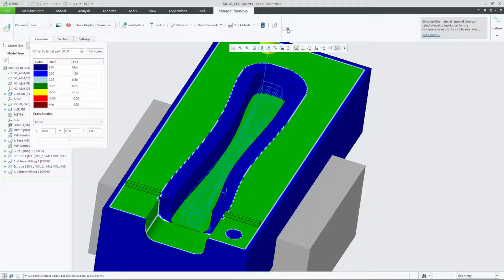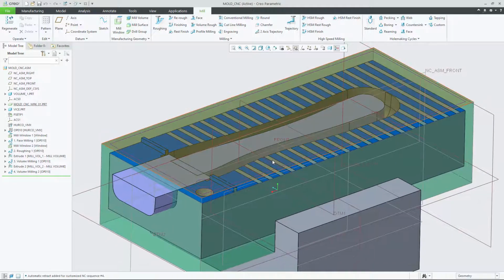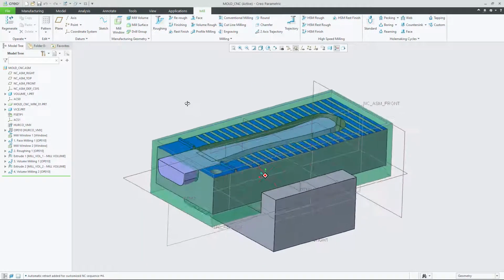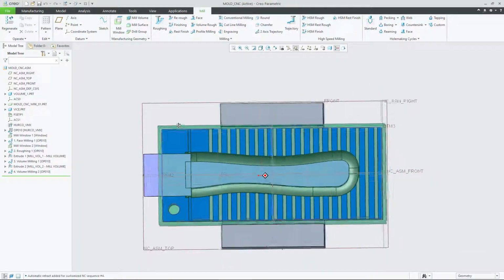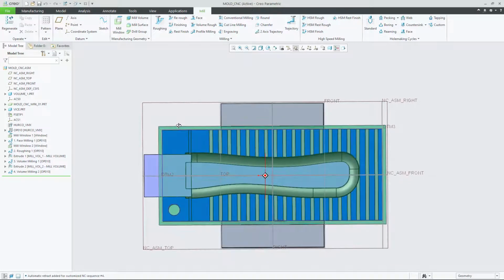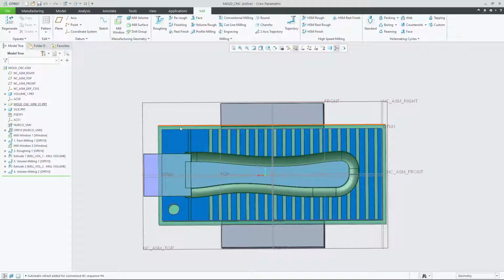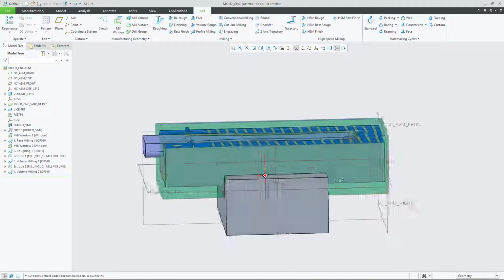So I'm just going to shut the sim down there, and now I'm ready to create a new sequence. So in this next milling sequence, we're going to address the material which is around the sides of our reference model. So if you remember back, we added a distance of material around all sides of our reference model. And now we want to remove that.